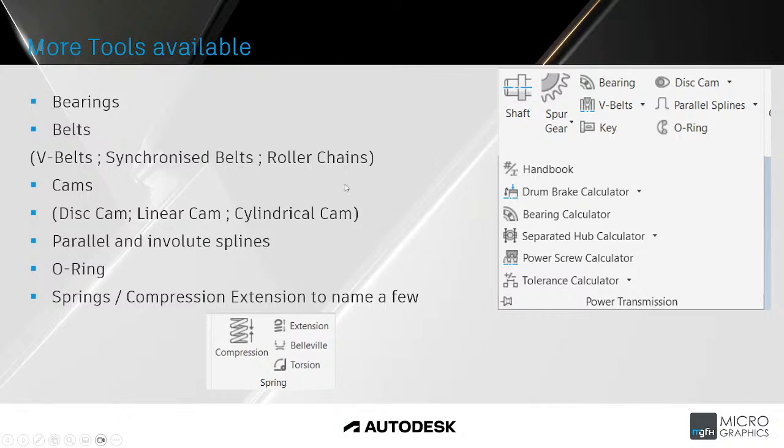So for me, the Design Accelerator is quite a very handy tool, as it creates the drawings for you. You can run simulations, you can run calculations, and to see, for instance, like I said previously in the shaft, you can actually see if the shaft will be able to withstand the specific load at a specific point. When you insert the pin with your calculation, you can actually see if you are selecting the correct size pin, the correct standard pin. So that is something of Design Accelerator that I really do enjoy using a lot, and I really do love it.